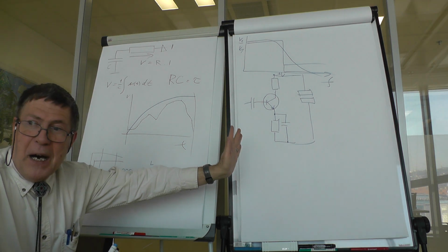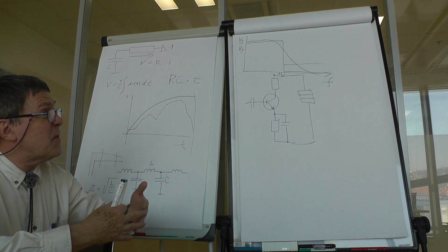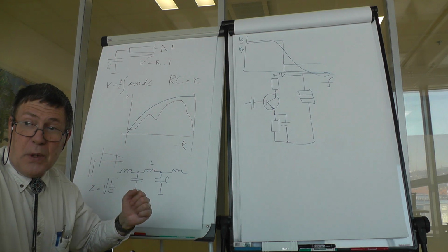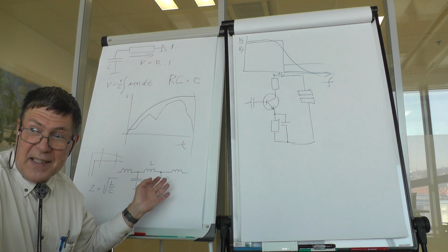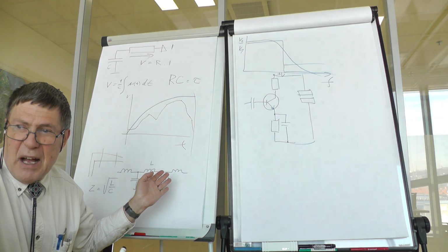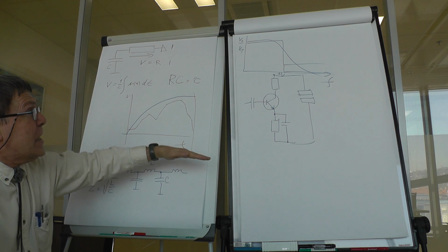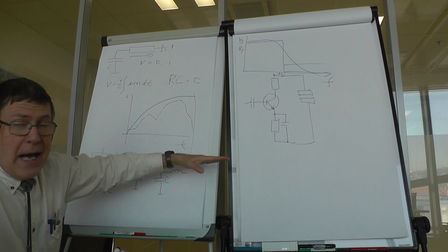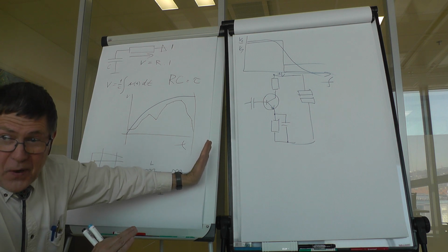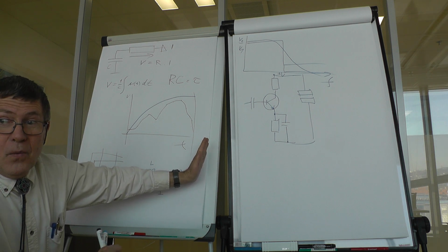You can speed it up by first calculating the DC operating point, let's say starting the calculations from pre-charging all the capacitors to the operating point, and that would shorten your calculations and at the same time decrease your numerical errors within the calculation. So this was the first introductory talk. We can solve more or less anything in time domain, provided that we can describe nonlinear elements in time domain.